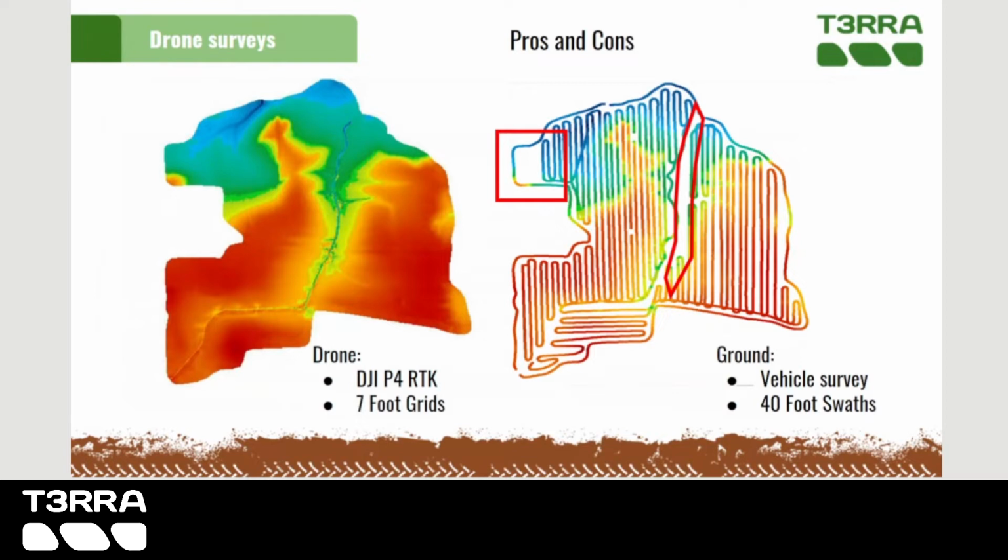But the drone elevation needs to be edited down to a manageable size in order not to overload the Terra software system. Ask providers for the point spacings to be between 7 to 10 feet upon export. The more points, the larger the file size and longer the processing time. Large files can be handled well in Terra Design, but can cause delays and lags if imported as a raw elevation map or control file for implementation in the in-cab software packages.